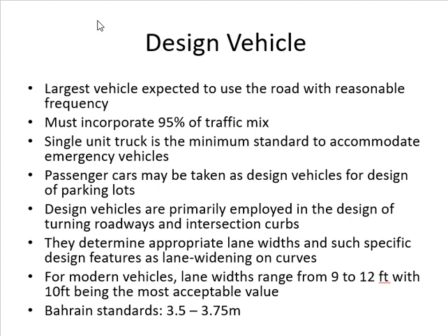If I ignore that one truck, how much traffic am I ignoring? 1%. So anything less than 5% can be ignored. Any vehicle which has less than 5% of the traffic can be ignored.